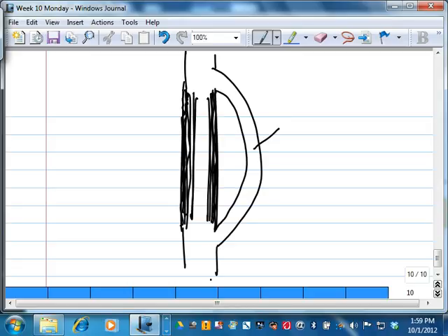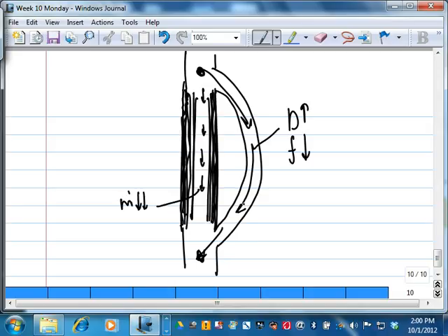So now it becomes flow in parallel, isn't it? Parallel pipes. So this one is still healthy. The diameter is good. The f is down. So they don't bother cutting this away. They still leave it there. But only a small amount goes here. The large amount goes down here, because the head loss between here and here is the same. Down the path with the narrow and very high friction, only a little bit. So m dot is small. Here, m dot is large. So that's the example there.